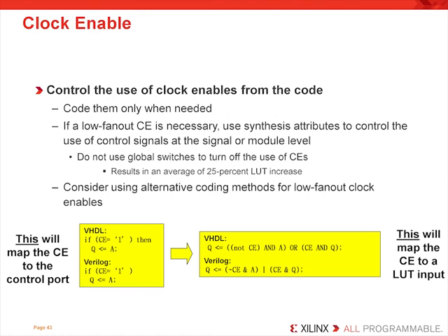Now please note, Xilinx is not recommending you design asynchronously. Just try to reduce designing low fan-out clock enable signals into your design, that is, clock enables that drive fewer than 8 registers. Synthesis tools will get smarter about when to use the dedicated clock enable control signals and when to move the clock enable to the data path, that is, to the LUT input, but it's going to take some time. You should also note that some synthesis tools allow the user to disable the use of the clock enable port on the register. Xilinx, again, does not recommend this, typically because on average it results in the use of 25% more LUTs and a waste of resources.